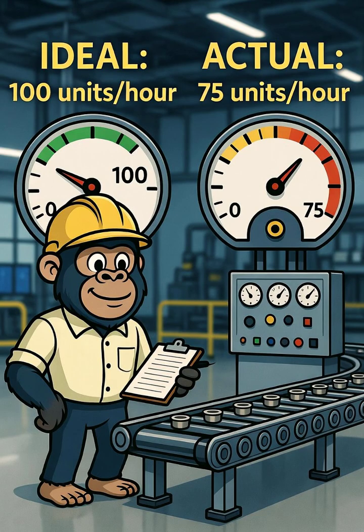Small stops. The machine keeps pausing for 5 seconds here, 10 seconds there. Maybe a sensor is acting up, or there's reduced speed. Maybe the operator slowed it down because the material is slightly off spec, and running full speed causes jams. Minor adjustments, stopping to tweak settings. Operator inefficiency. Maybe the new guy doesn't know the machine as well yet.